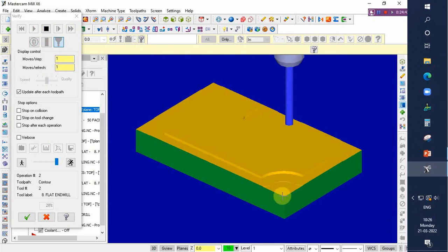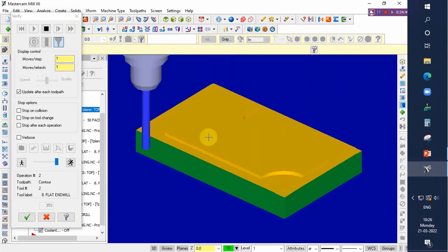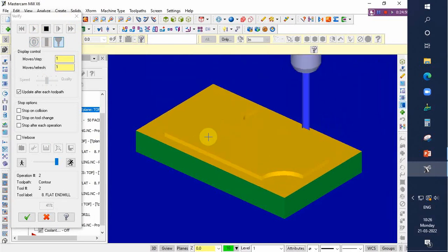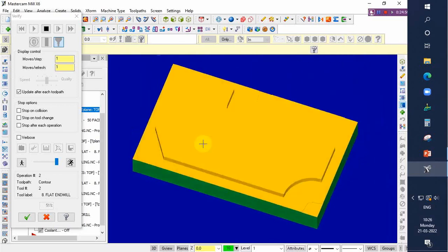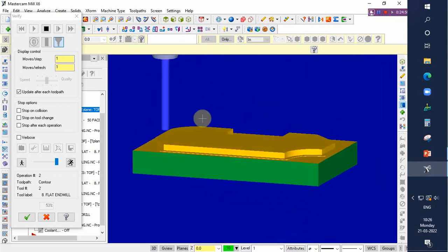Suppose we have material at the corners still, simply go to multi-passes option. We can increase the size. Say number of passes to be increased. Instead of 8, we go with 9, 10 like that. All the materials will be removed at 4 corners.